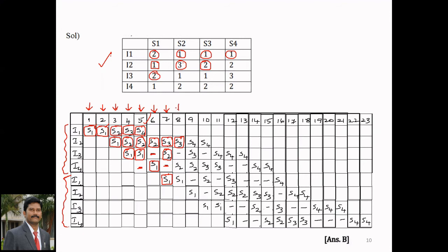At clock cycle 8, S3 is now completed. Even though S2 of I3 is completed, there is a stall here because S3 is already busy, so it should not start S3. Now I4 will enter S2 because S2 is free. And I1 takes 2 clock cycles according to the given data, so it continues S1 and S1.